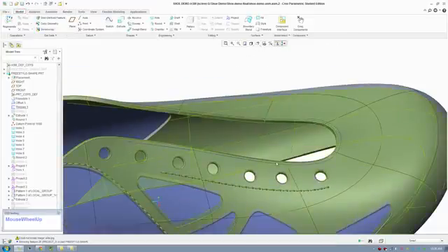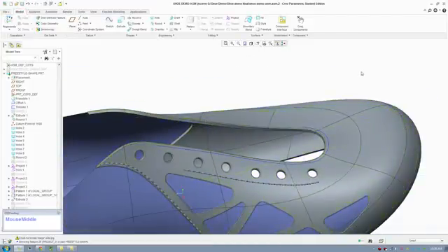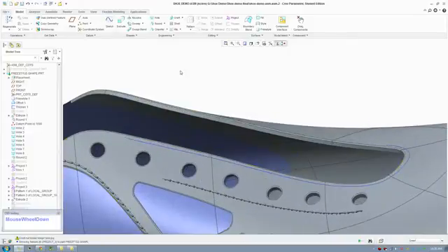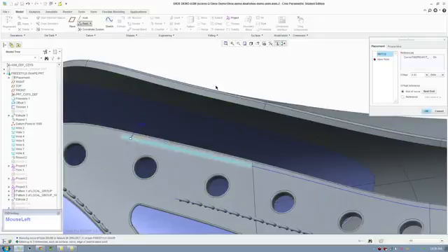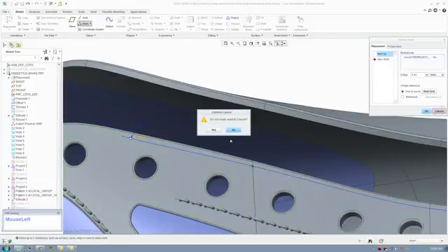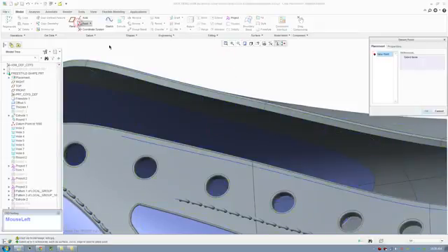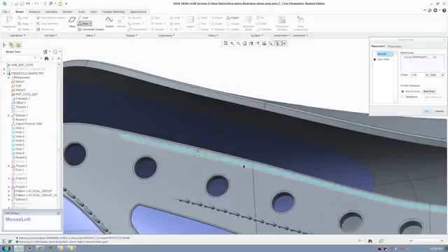I'll create the stitching on the top here. Alright, what you need to do is with the pattern tool, you can pattern along a dimension, and you're going to create a first point, a datum point. And what's really handy, when you click a point on the curve, make sure you click on the whole curve. This one's only going to that particular point. It's very important that you tap right click to select the whole curve.